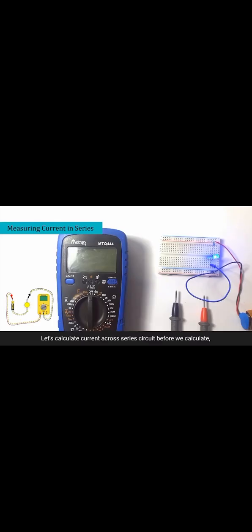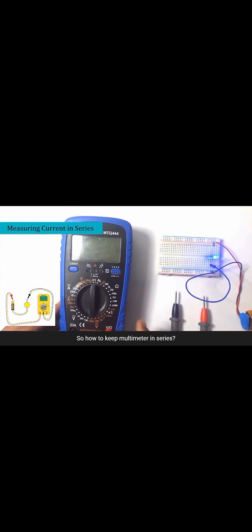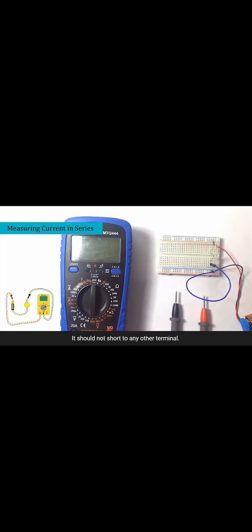Now let's calculate current across the series circuit. Before we calculate, we have to first understand that whenever we want to measure the current, we always have to keep the multimeter in series. So how to keep the multimeter in series? As you can see, this is a closed loop. I am disconnecting the positive terminal and connecting it to the center. Anywhere at the center you may like. Make sure it is not connected anywhere else. It should not short to any other terminals. You can connect it to any independent hole here.